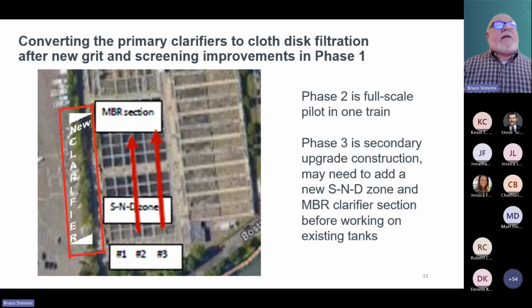And that's the big advantage, using that low pressure air to get the oxygen transfer into the biofilm. We can really reduce the overall energy compared to those, call them traditional processes, by 40 to 50% total. So it's a big number to look at when you consider MABR.